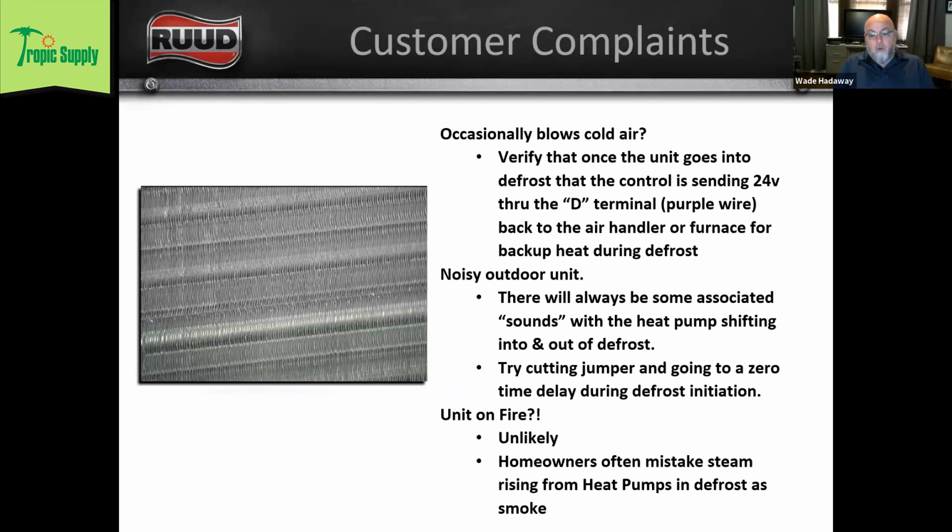Now, if it's happening before defrost and after defrost, or if it's happening during an off cycle, there's not a whole lot we can do about it. Cutting that delay wire is only going to help you if it's happening during the 30-second sound abatement. I don't want to make too big of a deal of it because it hasn't been a huge problem, but for those systems that experienced it, it was a big problem to them.